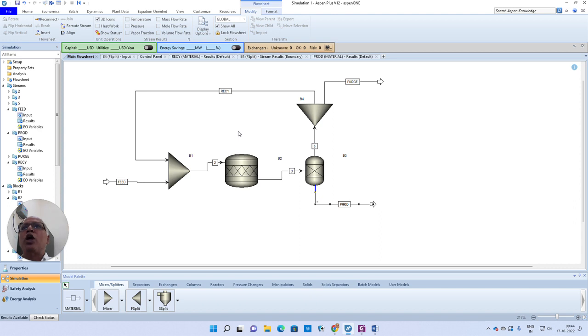So even for this small problem, first of all, unless and otherwise you decide on the type of tear stream, you will not be in a position to identify the computational sequence. In fact, there are a number of algorithms to decide on the tear stream, and even after deciding the tear stream, then only you will be in a position to calculate the computational sequence.